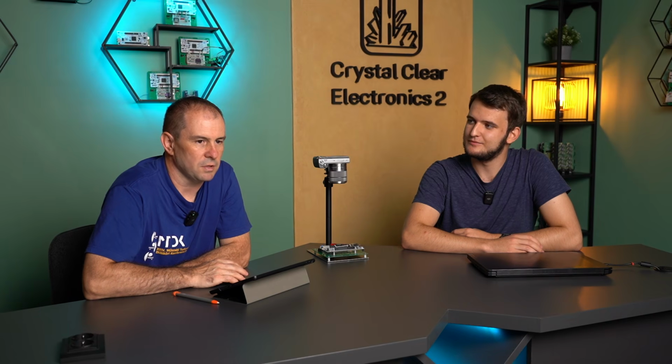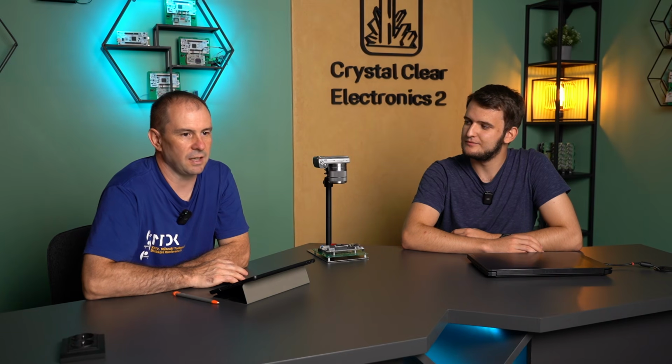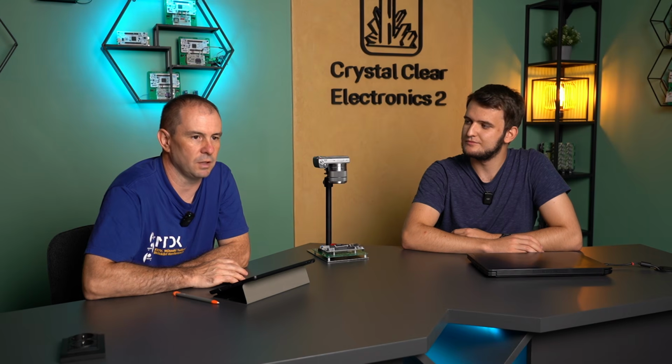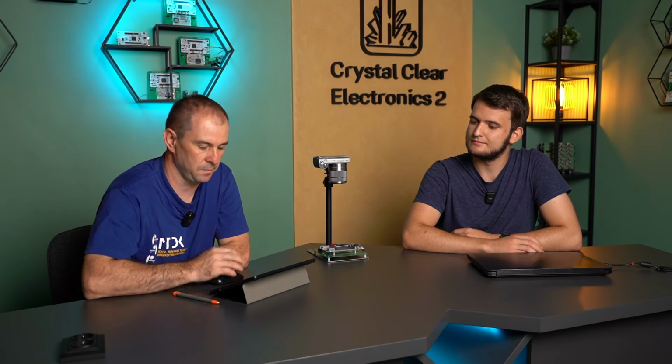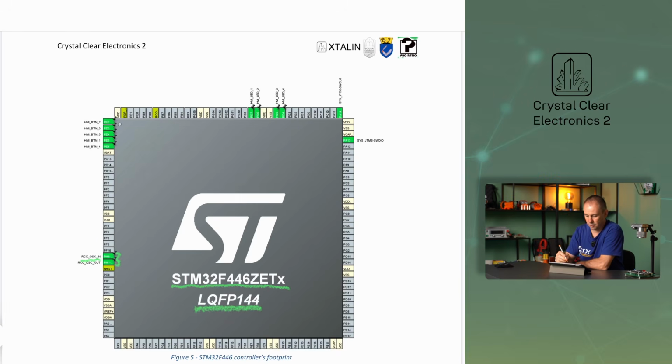If you already have a microcontroller and you want to control something, you have to load the program into its memory. In this chapter, we do this with the help of the SWD, or Serial Wire Debug interface. We use dedicated pins for this. PA14 is designated as SYS_JTCK-SWCLK. This is the clock signal. The PA13 pin is SYS_JTMS-SWDIO. This is the data input and output pin. And lastly, PB3 is SYS_JTDO-SWO, an optional signal through which the microcontroller can send data during debugging.